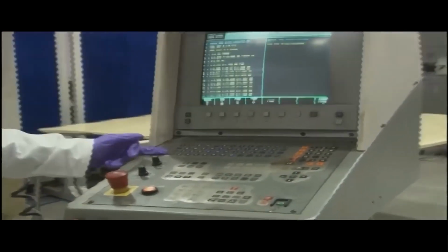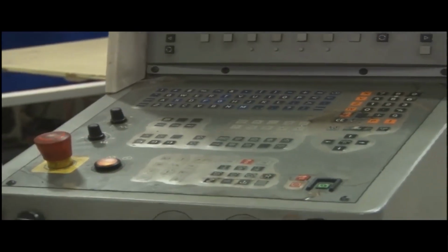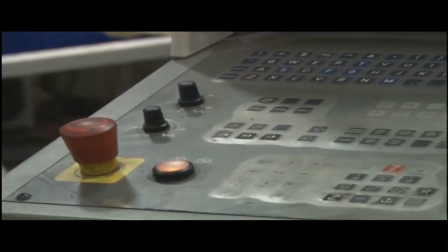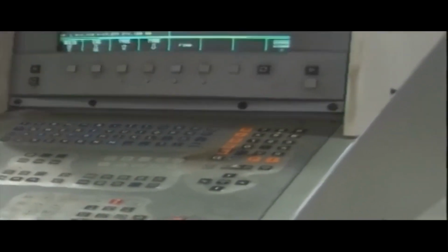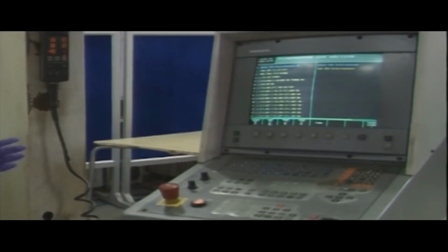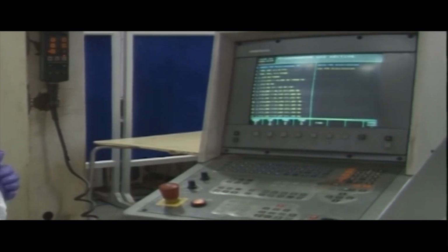Also, we can make small changes if we need, according to the machine setup. For that we have a control panel, we have the whole keypad here, and some important keys like these knobs. Feed override and feed underride can also be set. This is generally known as feed override. There is also the MDI, manual data input button. To find the references etc., we can feed some small codes to see whether the machine is running properly.